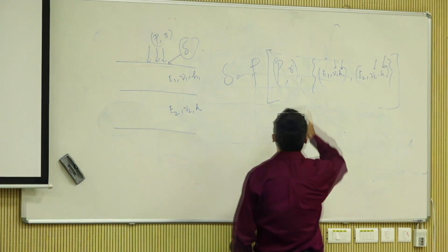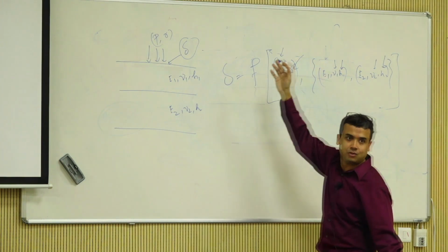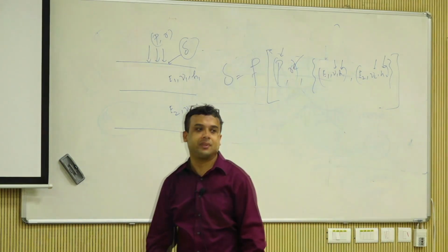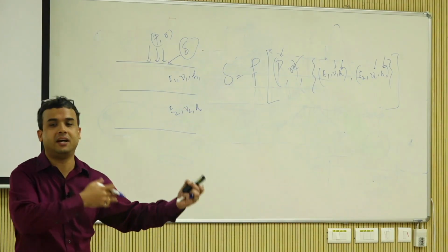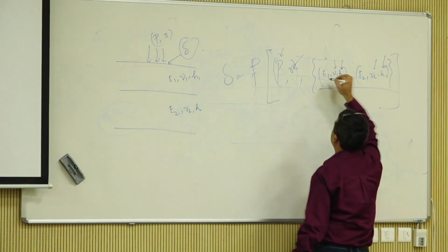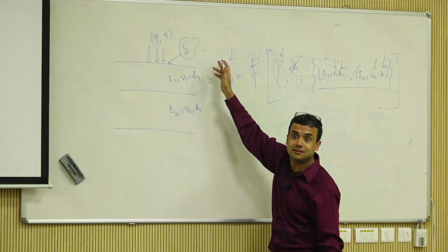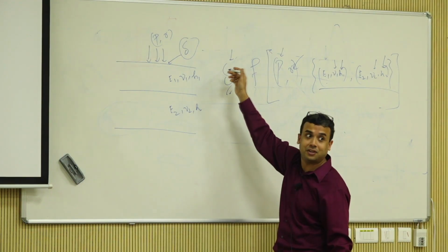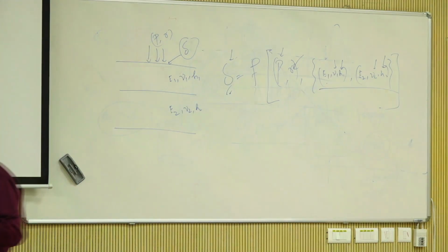You probably know this. Do you know P? Do you know R? Right? So what do you not know? E, right? So what you're going to do is you're going to back calculate the E. The forward calculation is when you have all the properties and you are trying to find deflection. Oh, by the way, in the field, do you know delta? Yes, because you're running an FWD test. You know the delta. So now you have delta and all the others, and you're going to try to back calculate the E. That's called falling weight deflectometer layer modulus back calculation. It's no rocket science.